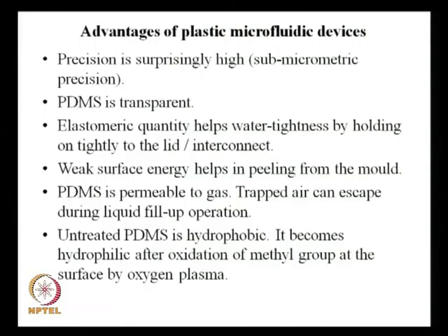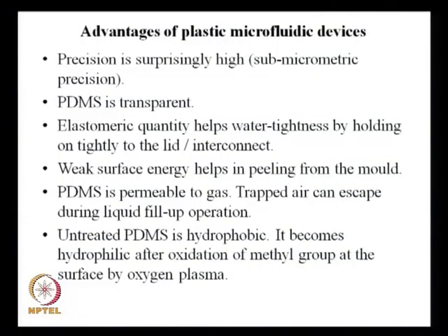The other point is untreated PDMS is hydrophobic. Hydrophobic means if you want to flow water through a PDMS channel, you will find resistance. If you had taken an inert channel of a similar size, you would find it easier for the liquid to flow through that channel. But since PDMS is hydrophobic, if you want to flow water through that channel, you have to overcome a higher pressure drop. That may not be good for your application, or it may be good for your application, you never know, it depends on what application you choose.